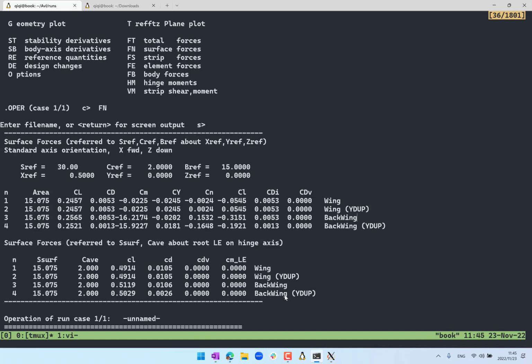But if the distance between the two airplanes is long, then the tilting of the thrust vector coming from the tow is so small that the amount of bank you need is almost negligible. And to counter the difference in yaw due to the different induced drag, you have to push your rudder a little bit. Again, let's just ignore these small things for now. You can calculate them, but they'll end up being pretty small.